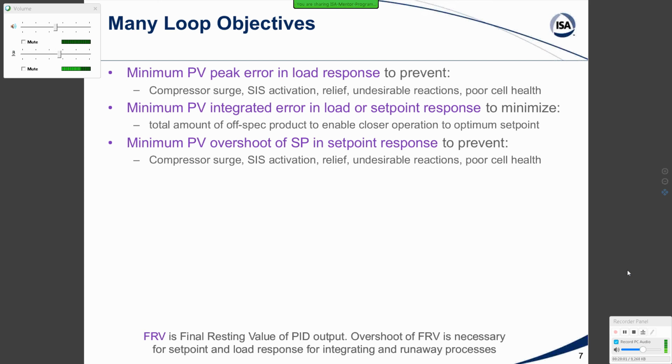And I have had some statements made, and I think this is a little extreme, that overshoots of pH of 0.02 pH are unhealthy. I think that it's hard to even measure that reasonably. So maybe it could be more like 0.04, 0.05 pH, but still an extreme sensitivity to overshoot. And they make set point changes in bioreactors in pH and temperature to move from promoting cell growth to promoting product formation. They call these temperature shifts or pH shifts. And when they make them, they don't care how long it takes to get there, but they don't want any overshoot.